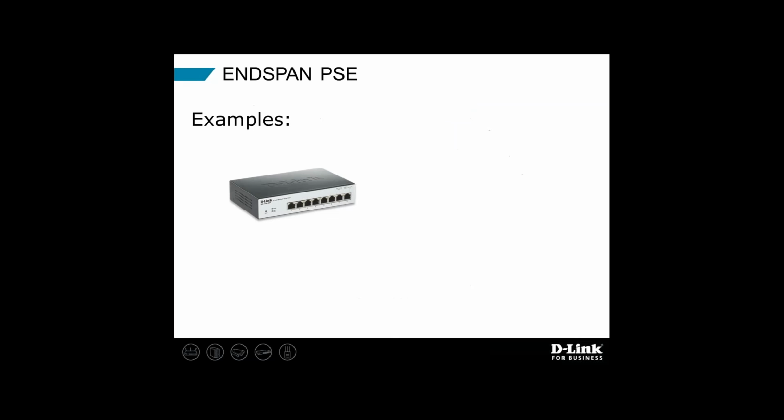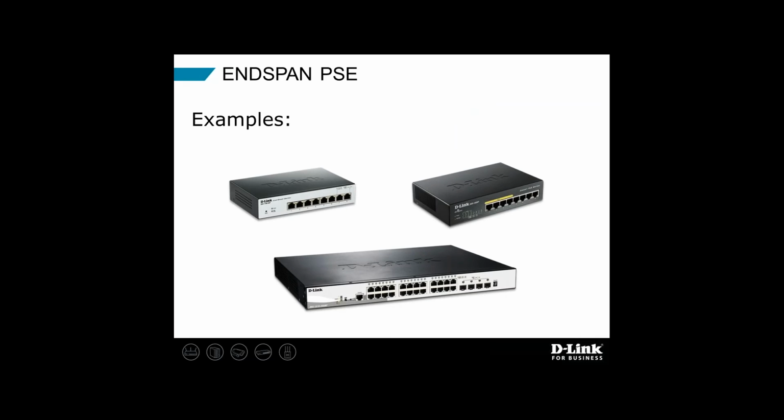Here's some examples of end-span PSEs. These are PoE switches. There's a couple 8 ports, there's a 24 port. These are end-span devices because they generate the Ethernet signal as well as act as a PSE by putting the power on the cable.